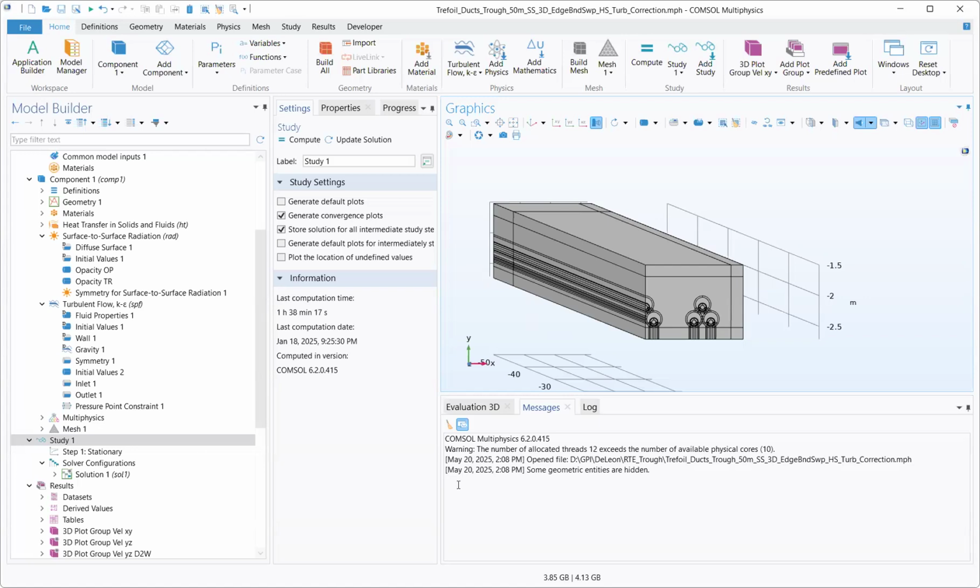Any other questions? Okay. One last thing is that in the laminar flow, because we have air going in and out and we're forcing the air, instead of open boundary, I use inlet and outlet. Remember, cable in air, the air is being heated and the fluid flow moves from top to bottom, right? In this case, we're forcing the air.